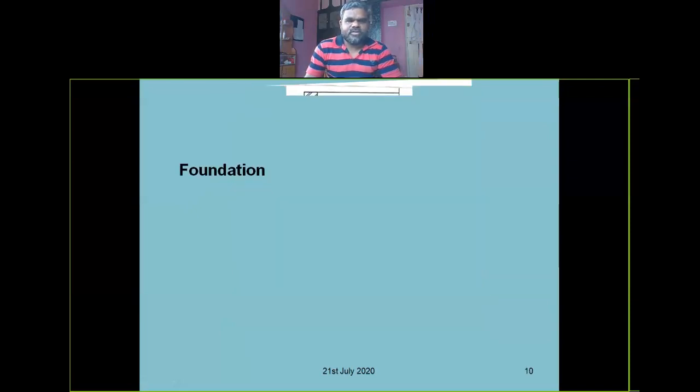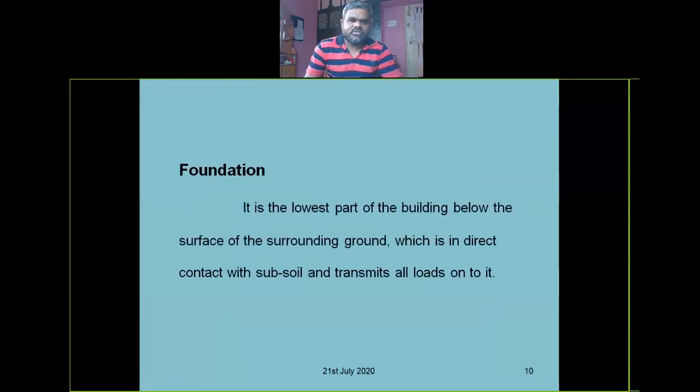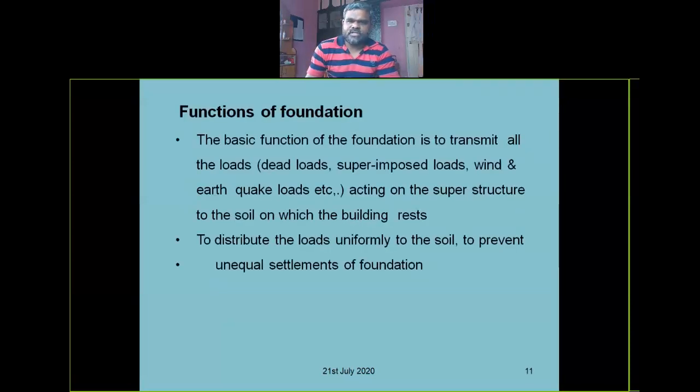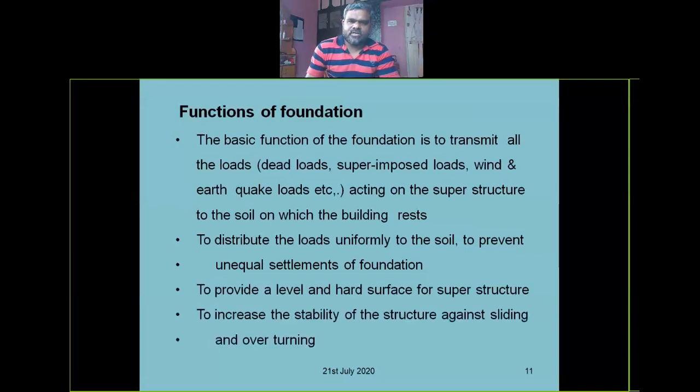Let us see the functions of one and all, right? So foundation: it is the lowest part of a building below the ground level of the surrounding ground, which is in direct contact with the soil strata, hard soil, and transmits all superstructure loads to the ground, right? The basic function of the foundation is to transmit all loads, whether dead loads, live loads, wind loads or earthquake loads acting on the superstructure, to the soil on which it is resting.